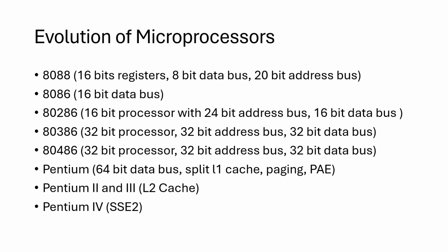After the 286, Intel introduced the 80386. This one has 32-bit registers and a 32-bit data bus, and it can address up to 4 billion bytes, which comes to approximately 4 gigabytes of memory. It supports protected mode as mentioned previously, and along with protected mode, this processor also supports something called virtual mode. In virtual mode, it is possible for the processor to swap portions of memory onto the disk. In this way, programs running concurrently can have space to operate.